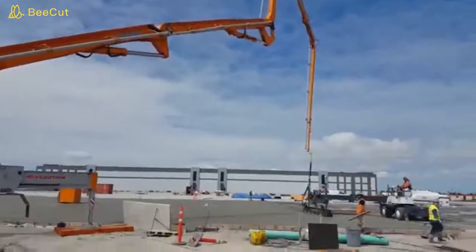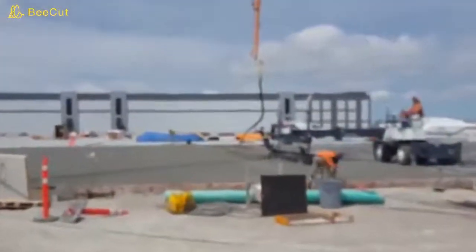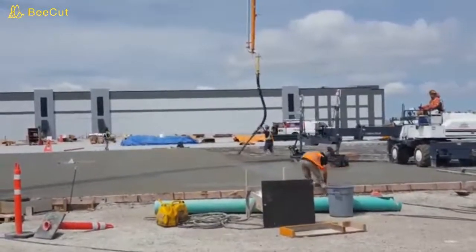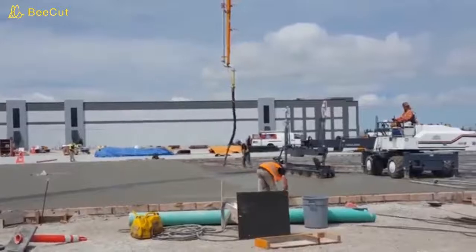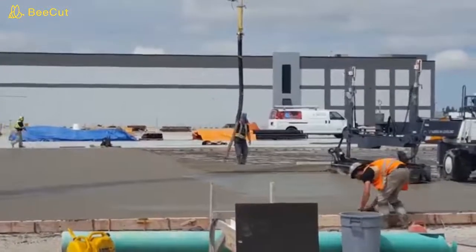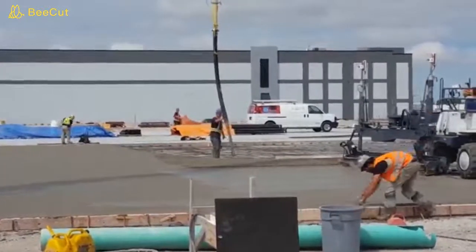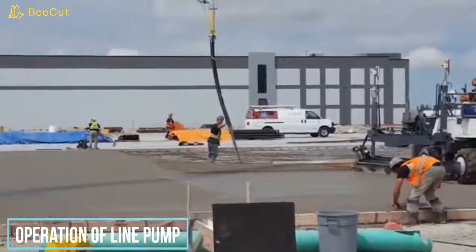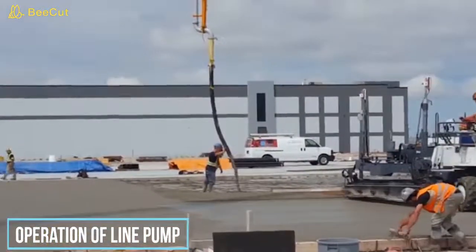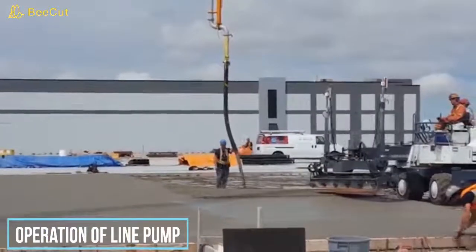For line pumps, a type based on support mounting, it is a versatile portable unit typically used to pump not only structural concrete but also grout, wet screeds, mortar, shotcrete, foam concrete, and sludge. Pump manufacturers offer a variety of different line pumps to meet a wide variety of needs. Line pumps typically employ valve type pumps, while the smaller models are often called grout pumps. Many can be used for structural concrete and shotcreting where low volume output is suitable.